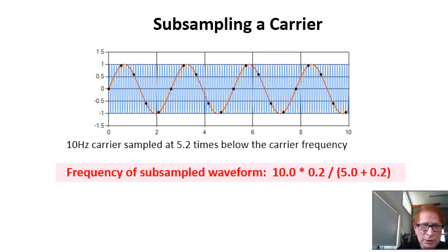So we are not alone in this goal to direct sample the RF. But is it really achievable? Can we subsample a 2.4 gigahertz carrier at 10.2 times or higher the carrier frequency? There's a good bit of literature on subsampling, but we haven't seen implementations of the type that we are proposing. The good news is that our methods are applicable even if the radio uses heterodyning to an intermediate frequency. But we will continue here under the assumption that subsampling is indeed practical. We look forward to hearing from you on this matter.